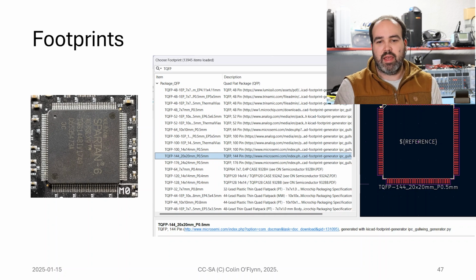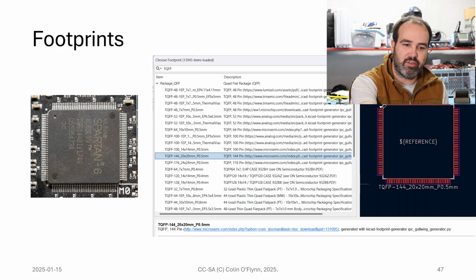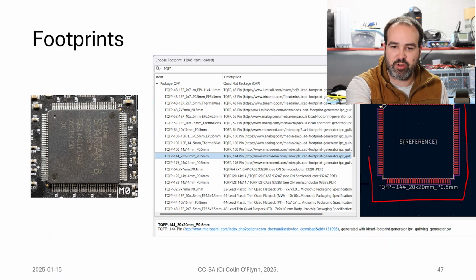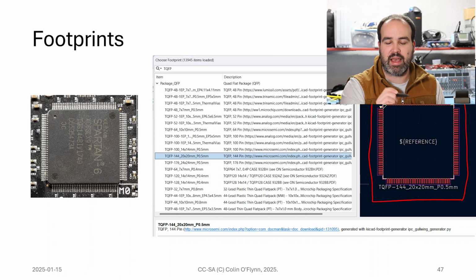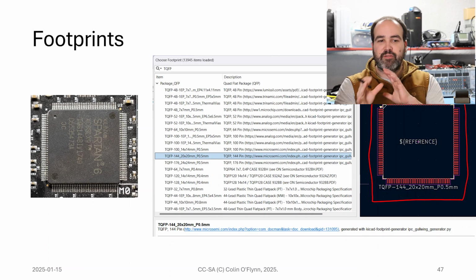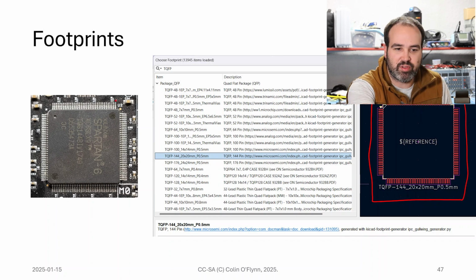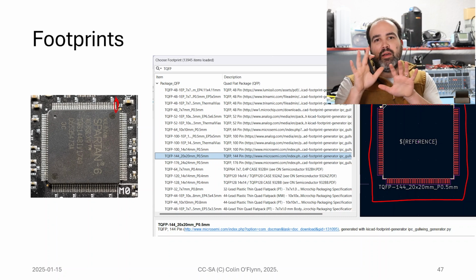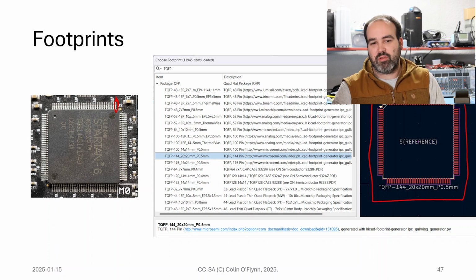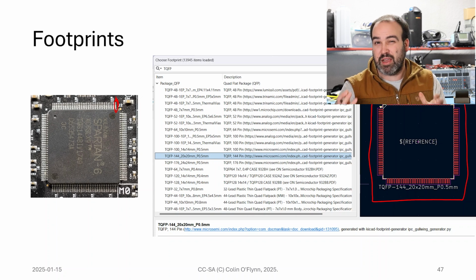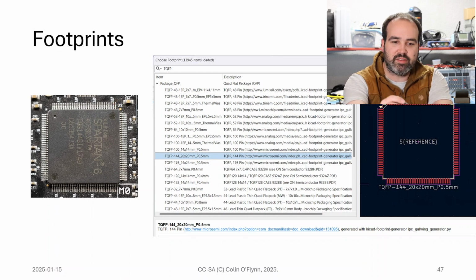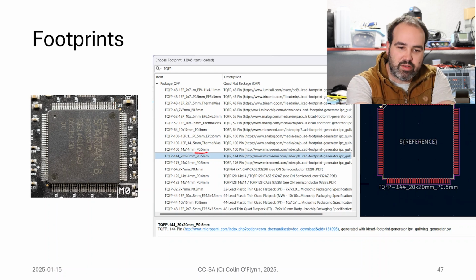Footprint. When we look at a part that has a PCB footprint, the footprint is these little copper pads that it'll fit on. The footprint is designed to provide reliable soldering, so it's a little bit bigger than the leads on the parts. How much bigger is generally defined by some specs related to reliable soldering. The one thing I will mention is that when you select a part, you sometimes will have a choice.